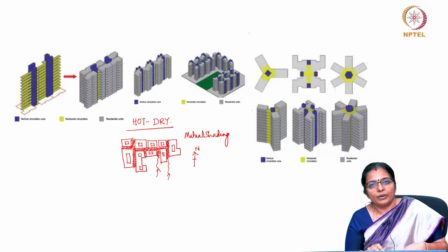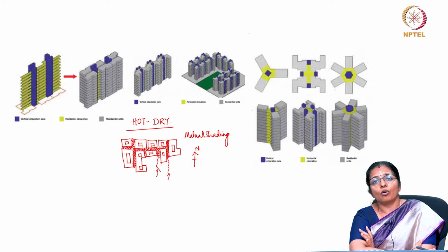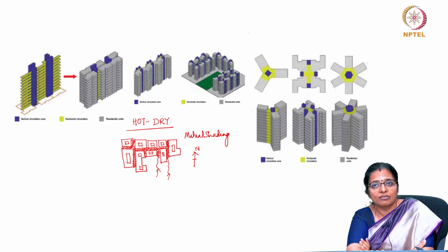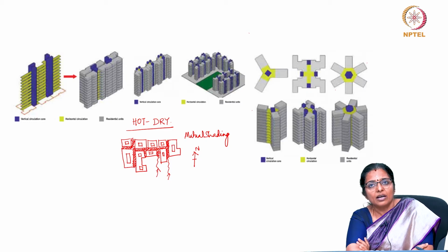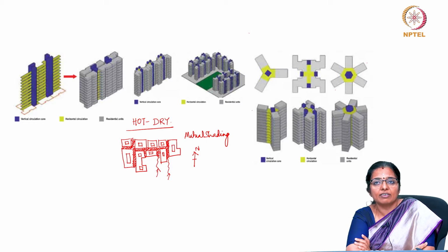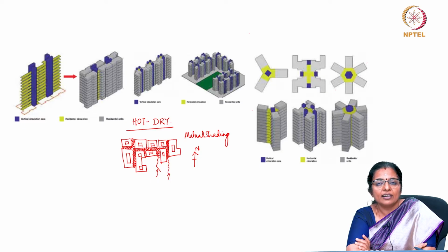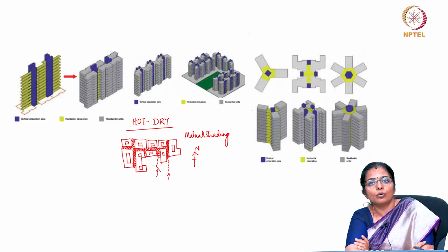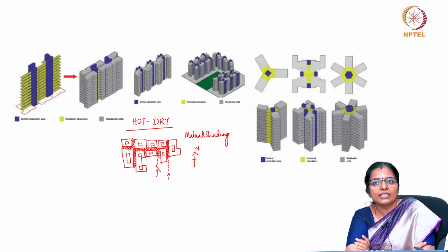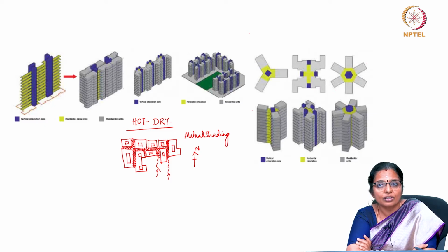In the warm humid climate, shading of the east and west elevations is difficult because of the low sun and may require special devices, whereas the south and north sides can easily be protected by an overhanging roof. Thus, the best orientation to minimize solar exposure on vertical surfaces is the longer facades facing north and south.